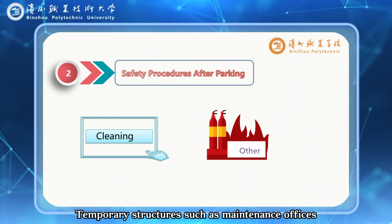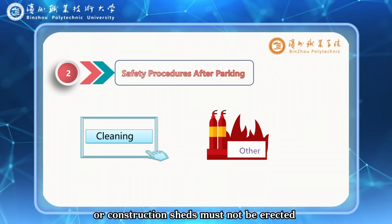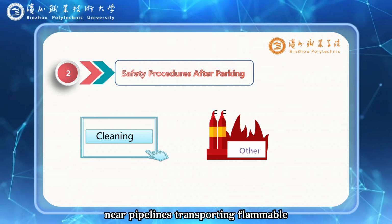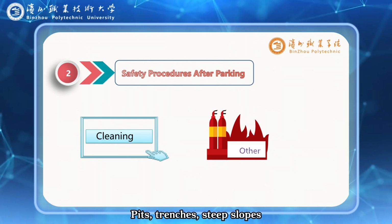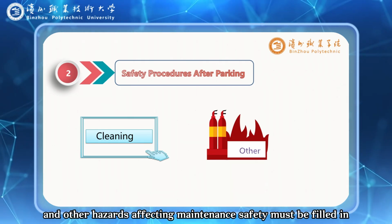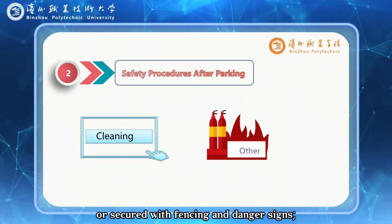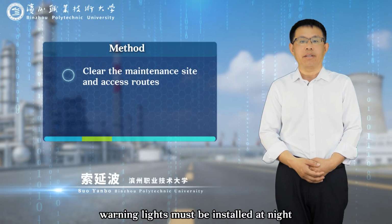Temporary structures, such as maintenance offices, rest areas, warehouses, or construction sheds, must not be erected near pipelines transporting flammable, explosive, or toxic substances. Pits, trenches, steep slopes, and other hazards affecting maintenance safety must be filled in, covered with ground-level grading, or secured with fencing and danger signs. Warning lights must be installed at night.